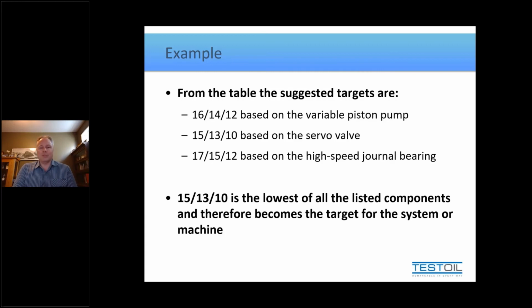And that's one of the other issues that we have when people start looking into their fluid cleanliness: they start setting goals that are almost unachievable or will frequently be an alarm. So my point is to make sure that you've set the target in a way that's realistic. According to the tightest clearance component, you'll get that from the chart. But then look at what it says for filtration recommendations. You'll understand if that target is achievable using your current filtration setup and maybe what you might have to change.